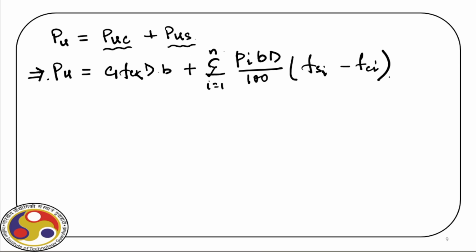So as you can see, for this problem, we have quantified the axial capacity. Now the remaining part is the bending capacity, right? For that, again, we will take the moment of the forces about the neutral axis, and that will give us the moment capacity of the section. But before that, let us modify this.